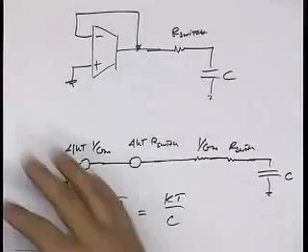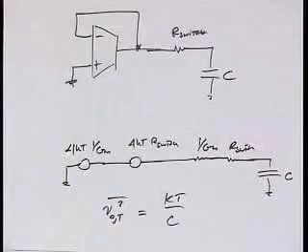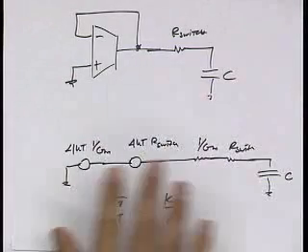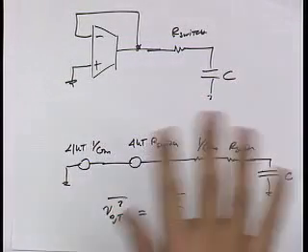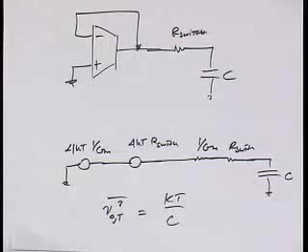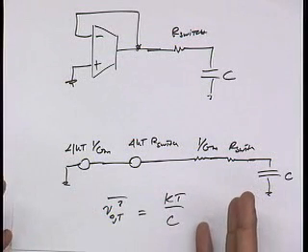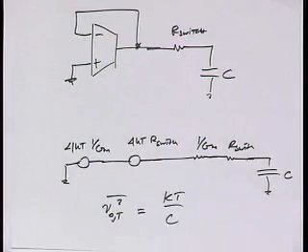I actually would prefer not to use a buffer in order to get the best noise. Now, this is a very simplified calculation. So, of course, if you do the calculation more precisely, you'll find the noise is slightly higher than this, right? Because we ignored a lot of details of the noise of this device. But definitely the result is the same. That actually the OTA does have lower noise. Okay.